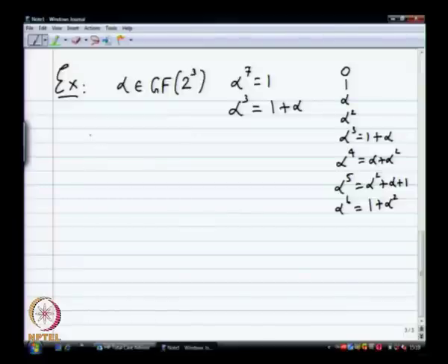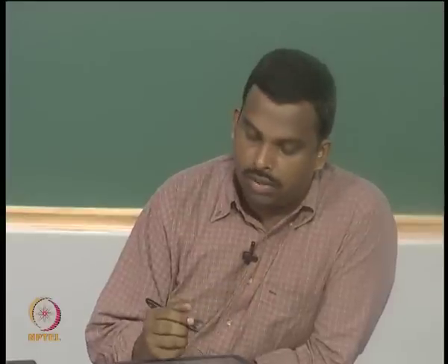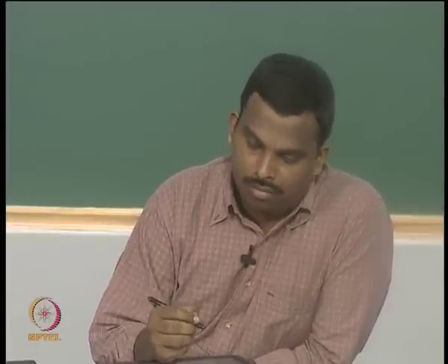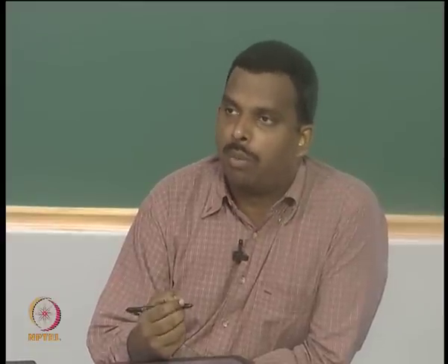Let us say n equals 7 and t equals 2. N is 7 and t is 2, what are the 4 roots? The 4 roots of my code, or 4 zeros of my code, sorry, are alpha, alpha square, alpha power 3 and alpha power 4. So, those are the 4 zeros of my code. If I have any code word or any received word, I will compute syndrome by plugging in alpha, alpha square, alpha power 3 and alpha power 4.